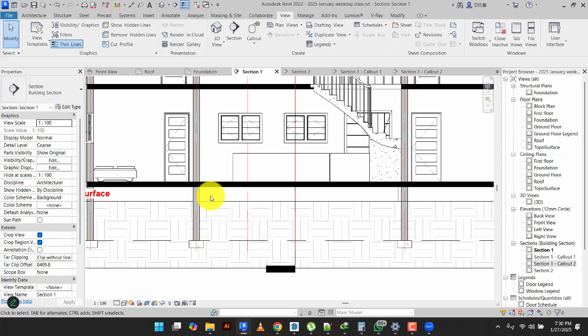You get it? So to fill it, that's when we use what we call filled region, right? So you come and draw the area you want to fill, and that hash thing for filling will appear.